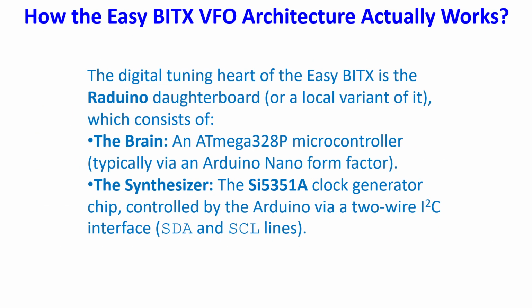How the ECBTX VFO architecture actually works. The digital tuning heart of the ECBTX is the Arduino daughter board, which I had shown earlier, or a local variant of it, which consists of the brain, an ATmega328P microcontroller, typically via an Arduino Nano form factor. My ECBTX has an Arduino Nano. The synthesizer, SI5351A clock generator chip, is controlled by the Arduino via a 2-wire I2C interface, SDA and SCL lines.